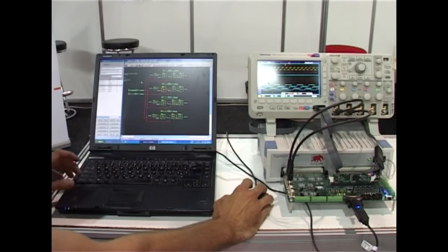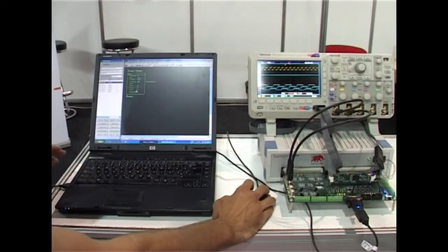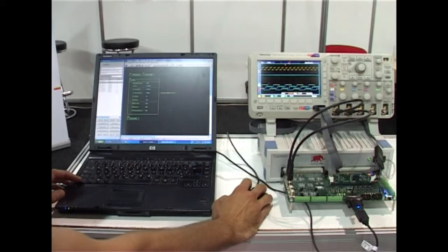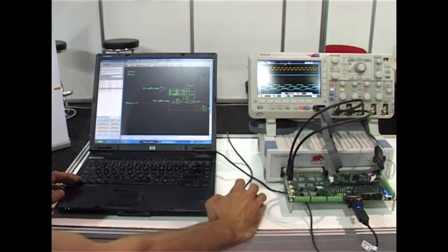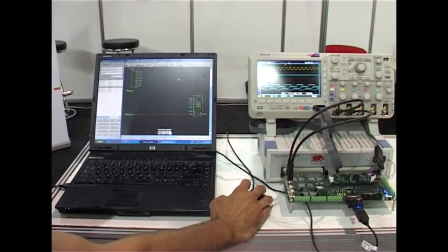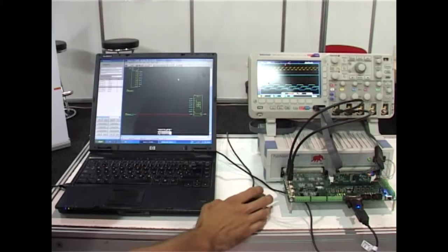The main advantage of our application developing environment is that it is totally deterministic. You define the period of your tasks in a number of processor cycles, and you define the order of execution of your elements. So you know exactly when something happens and in which order things are executed. After you create your application program, you download it to the microcontroller through a serial connection.